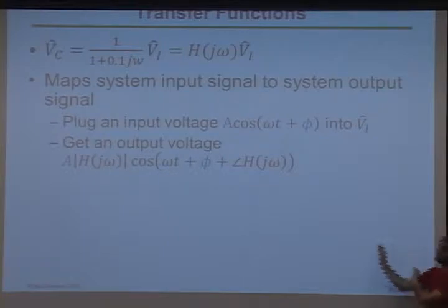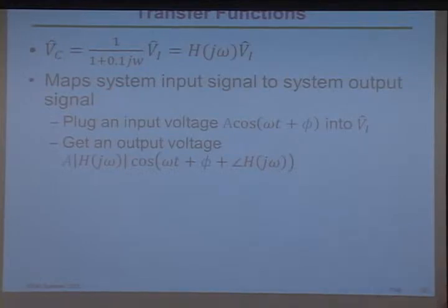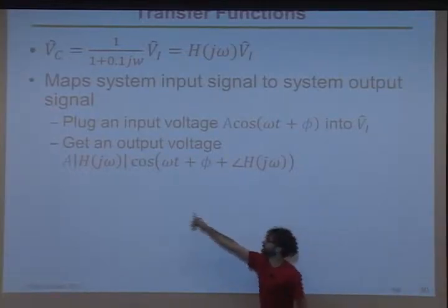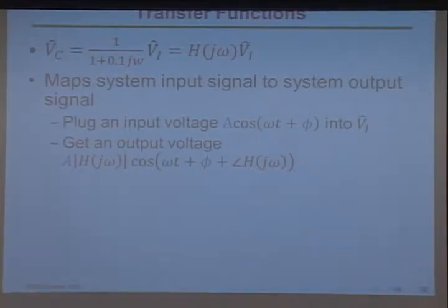And the phase will shift a little. So you'll have the original phase plus whatever the filter or the device wants to do to it based on the frequency. The key thing here is, whereas before we'd have a number like 3 or 5, now it's going to be a function of omega. So if you want to know how a particular signal reacts, you can plug in that omega.